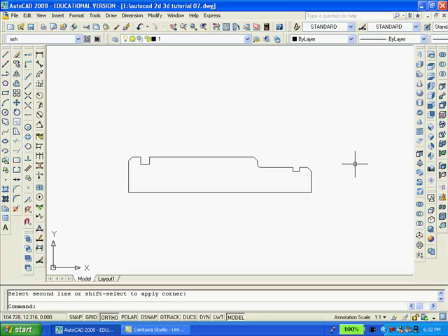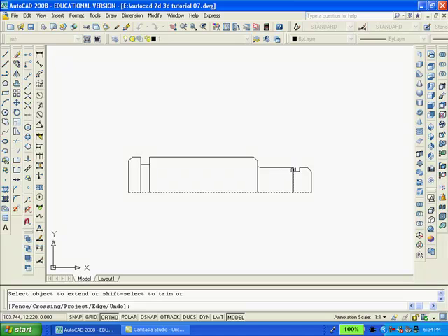This is going to be an outside view of the shaft, so I really have to draw a bunch of vertical lines. There's a lot of ways to do it, but in the interest of saving time, I'll use the easiest method. All I'm doing is extending to the center line all these vertical lines.